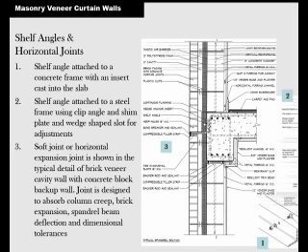Here at each floor, you're going to have this metal angle that's bolted into your structure. You'll also have flashing that comes out over that insulation. You'll have caulking right here. Then you'll have your bricks going on up to the next floor. These are the metal ties that are every so often to hold the brick back to the structure so it doesn't just fly off. Here's a picture of the metal angle, how that might be attached.